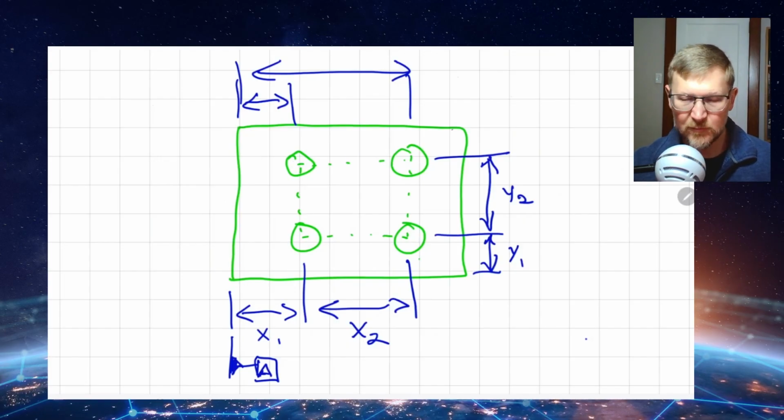And those tolerances can be different, right? I can accept the whole pattern can move a little bit to one side or the other, but I want the holes distance to distance being consistent. And so there's this ordinate approach, and then there's this more chain approach where you do one after the other.